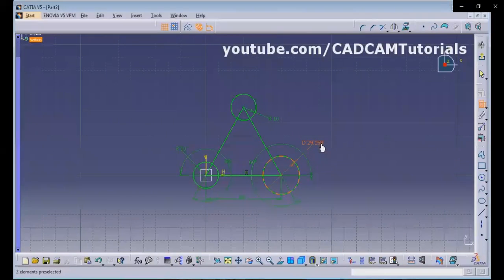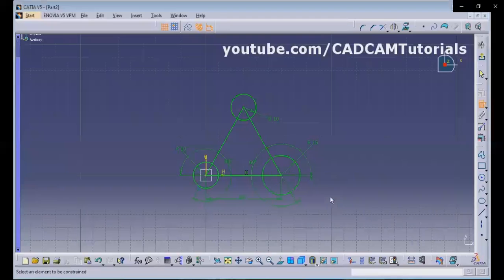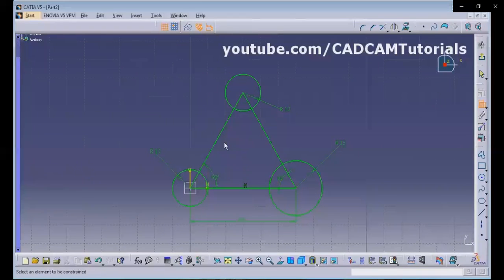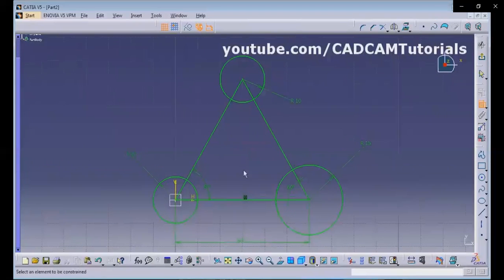Here is 15, so give 15 radius, press enter. In this way it is ready. If you want to zoom by mouse, then you have to press the scroll, right click and drag the mouse. In that way you can zoom the object using mouse.